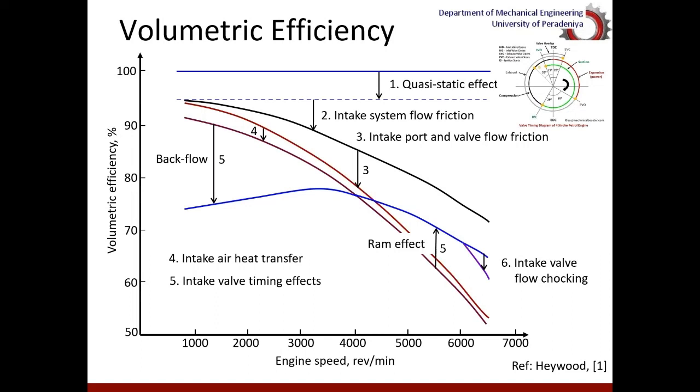When the mixture comes into the cylinder, there can also be a certain degree of heat transfer, which would heat up the gases and drop the density, also reducing the volumetric efficiency.